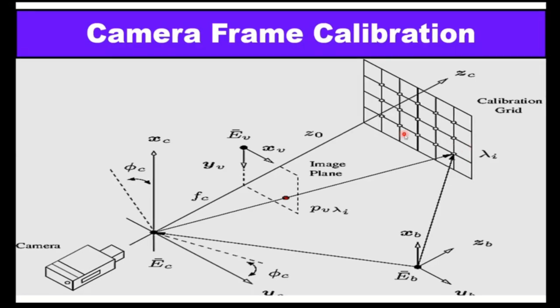External calibration grids place this grid on the camera lens or view, or software generated calibration grids are there. Once you generate the grid, your image will be placed on this. This is very essential because we need a coordinate system on the image to perform the measurements and later programming operations.